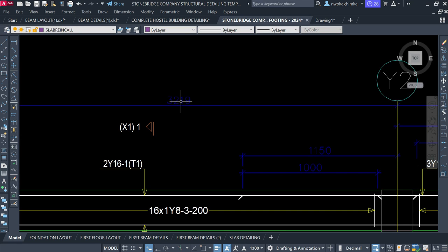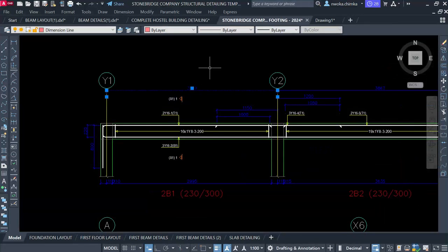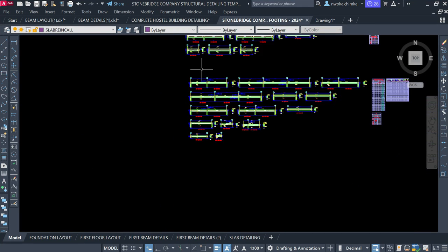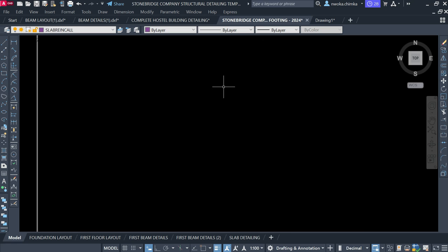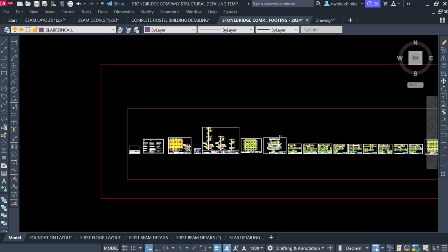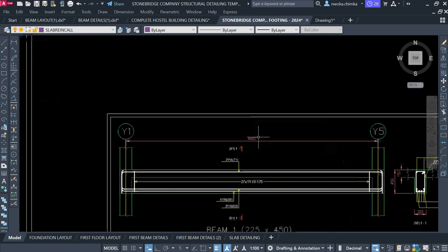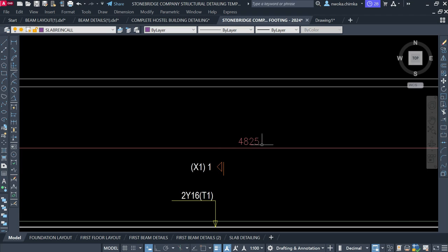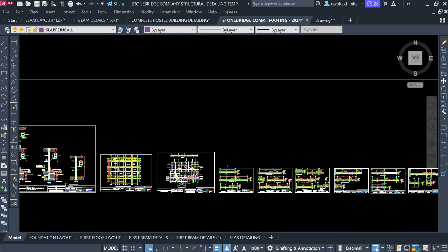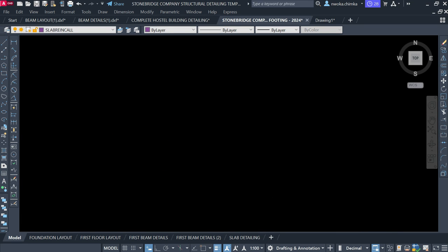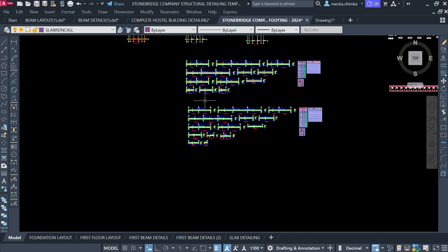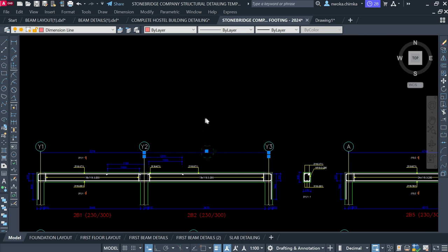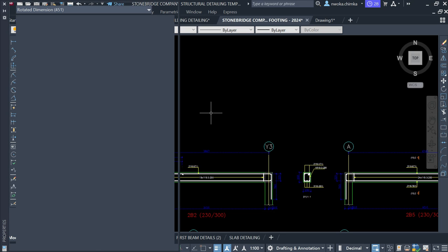So if I come here and begin to work on my drawings to make sure that what is here looks exactly like this sample that was given to me. This sample has a different color. So if I want to change to this color, I'll click here, come to this place and click on my dimension. Right click here and then say similar, then CH, enter.